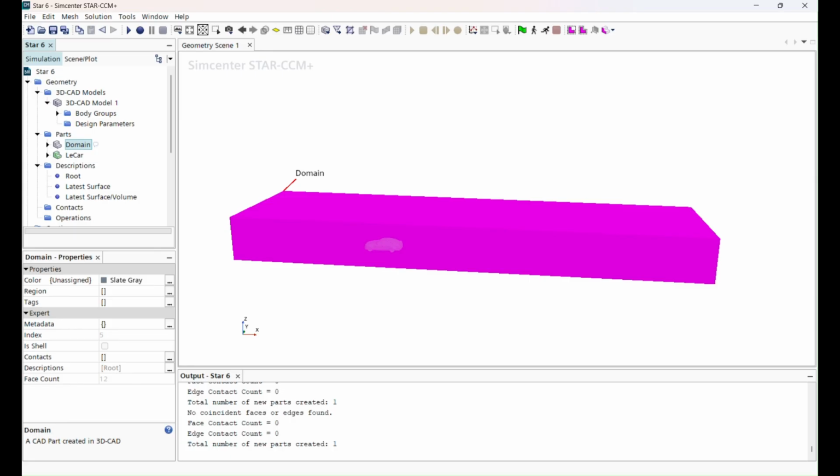You will then mesh it, which the computer will then have to run and iterate through to yield those solutions for you. So you want a good balance between giving your car that ample domain and space it needs to really give you accurate results, while at the same time not giving it too big of a domain that it will be computationally exhausting for the solver to iterate through and will increase that computational cost.